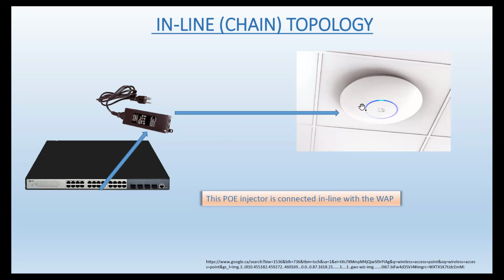Some of them come with a power transformer or power supply that needs to be plugged in here, and the other part has to be plugged into the 110 regular outlet. Do we have one in the ceiling? Usually we don't. Two ways: getting an electrician to install an outlet in the proximity so the power supply can be plugged in, but that costs a lot of money.